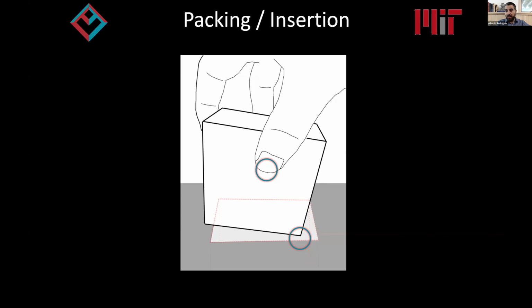So we have to rely on learning policies that are searching for the right kind of tactile interactions that are informative. But the interaction between the gripper and the object is still something that we can control. So we want to search for the right alignment between the object and the hole, while making sure that the gripper and the object stay in some stable equilibrium, in some stable grasp.